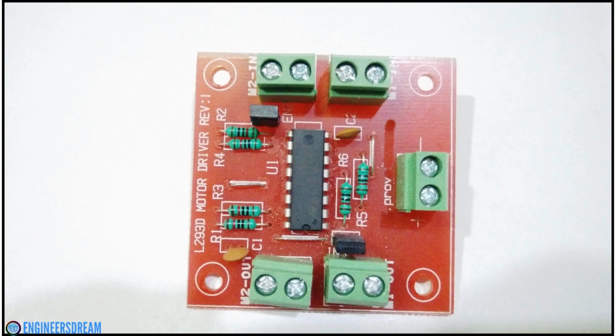The advantage that I found of using this motor driver is that I did not have to give 5 volts of supply separately to this motor driver breakout from my Arduino, because the circuitry of this breakout board is made in such a way that the VCC and the enable pins get the required 5 volts from the external battery itself. So in short, the motor driver basically converts the incoming supply from the battery and gives 5 volts of power to the pins that require 5 volts.